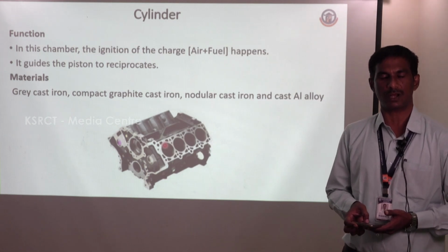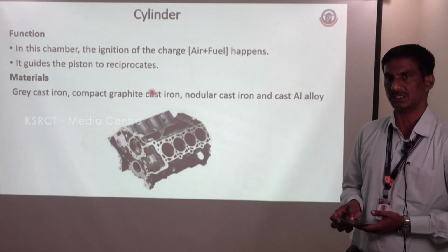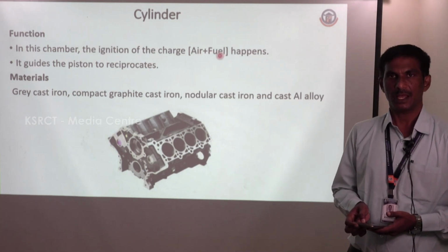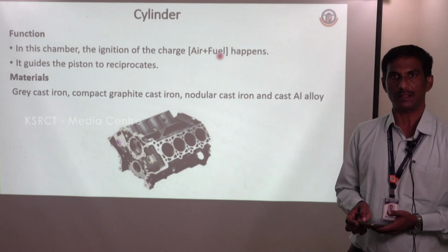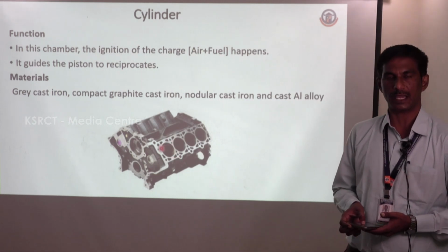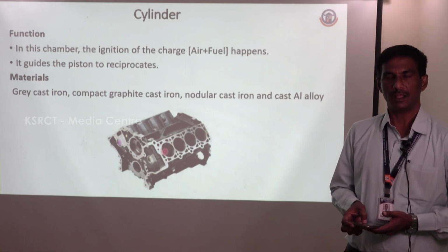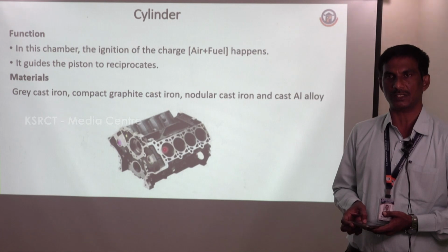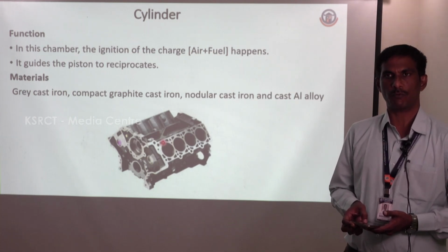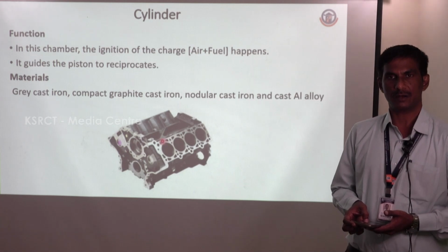Then the combustion, in the IC engine, two things are happening there. One is the chemical energy. Chemical energy is the air and fuel mixture. That chemical energy is converted into thermal energy, that is called heat energy. That is happening in the cylinder. Then that heat energy is converted into mechanical energy, that is also happening in the cylinder. So the cylinder block should withstand both the mechanical forces and also the thermal forces.